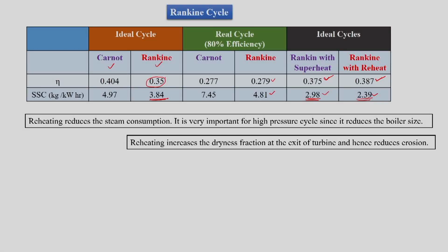This point we should note, since we were saying that we were not supposed to have superheat if we have high pressure water as the source. But in that case reheat is possible, since reheat happens at lower pressures, where we will have sufficient temperature difference, and then we can further increase the efficiency.